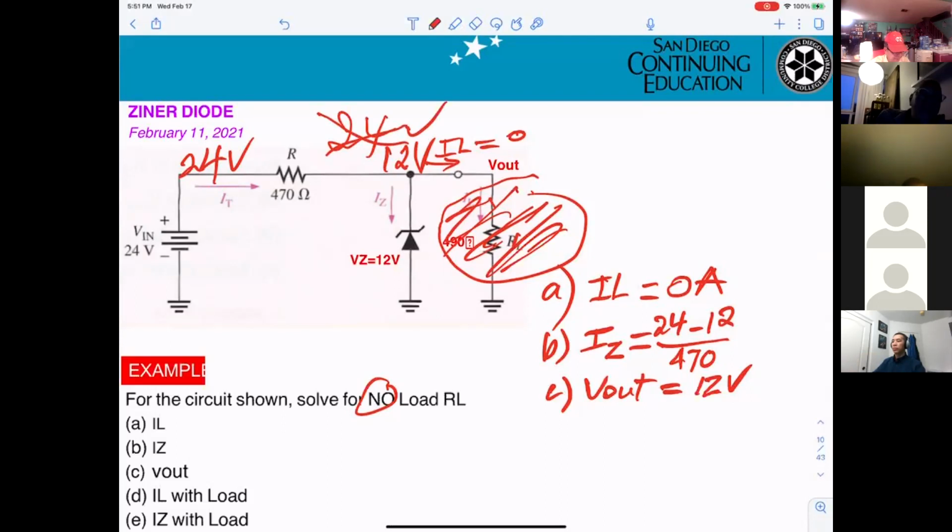Oh, right. Okay, I see. You subtract it from the 24 volts. No, it's not subtract. I think he's talking about the voltage drop across the resistor. In this case, VZ is 12 volts, then V out will be 12. However, if I change it to VZ equal 5.1 volts, what is V out? 5.1, they equal the breakdown voltage, VZ.